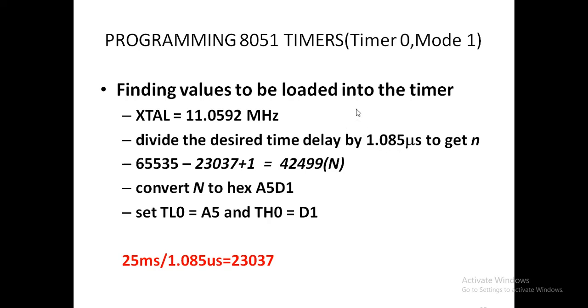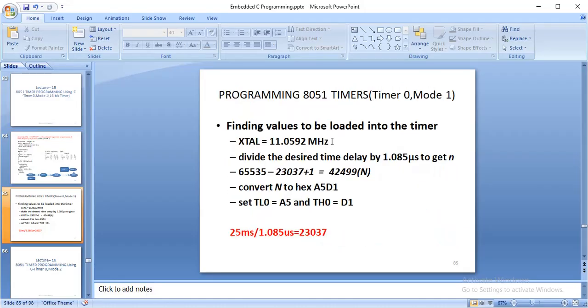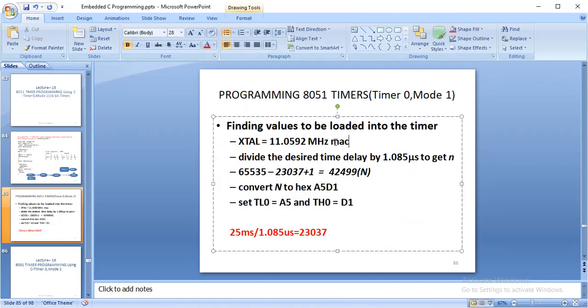Usually for an assembly language program, for example MOV A, B, it is an instruction. How much time it takes to execute is defined with the help of machine cycles. They will not tell us 2 microseconds it will take to execute; they simply say how many machine cycles it takes to execute that particular instruction. How to calculate that machine cycle?